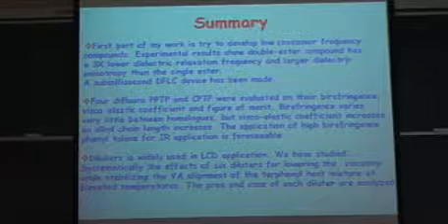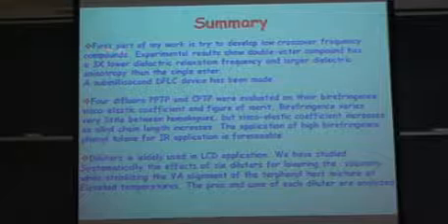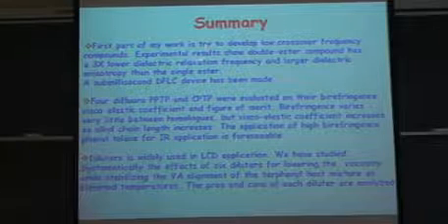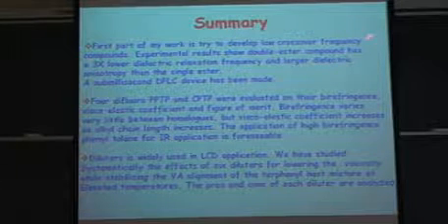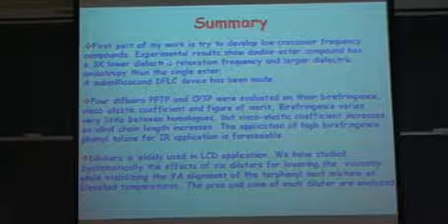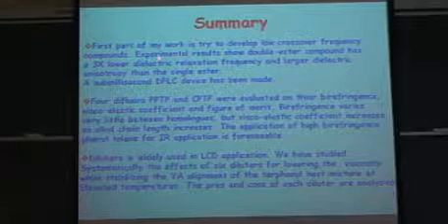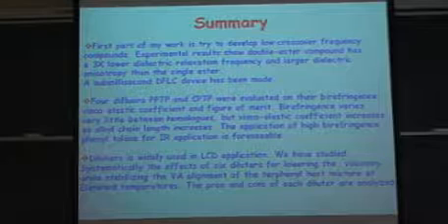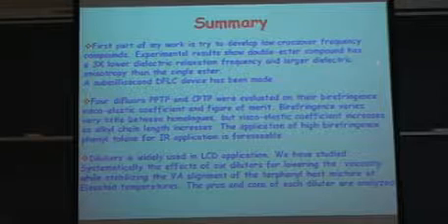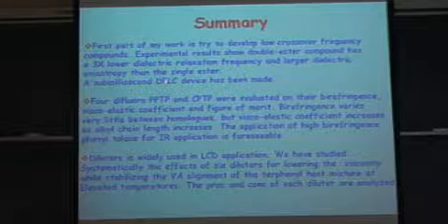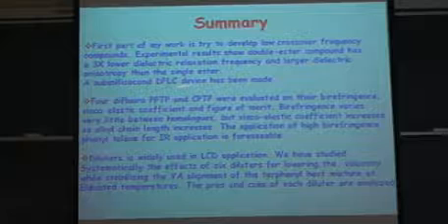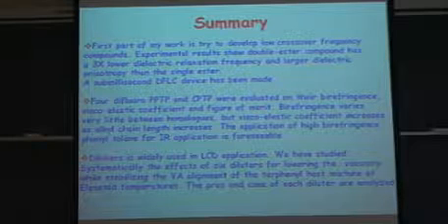Okay. Finally, this is a summary. The first part of my work is trying to develop low crossover frequency compounds. Experimental results show the double ester compound has 3 times lower dielectric relaxation frequency and larger dielectric anisotropy than a single ester. And the sub-millisecond DFRC device has been made.